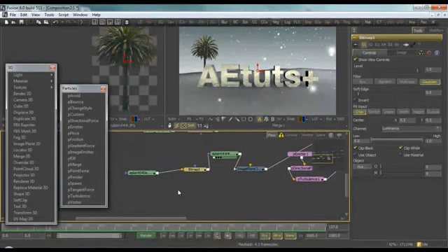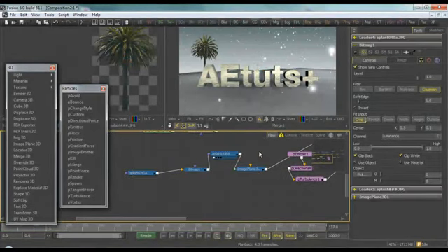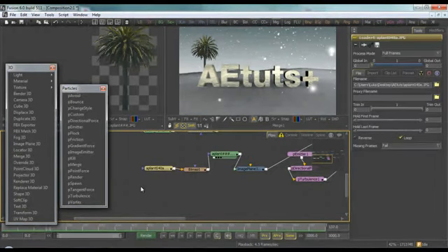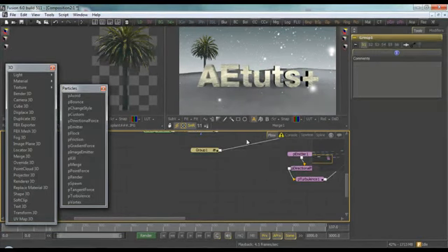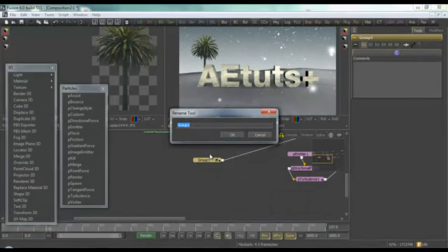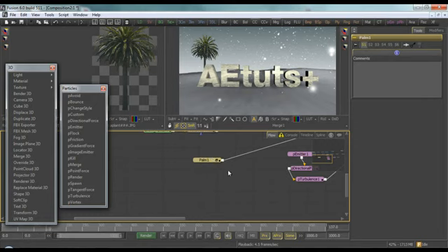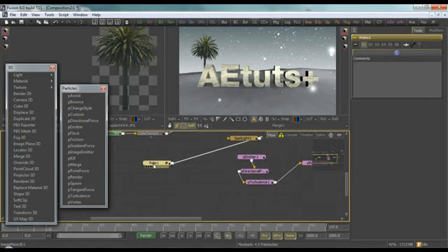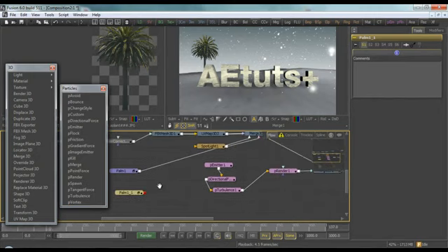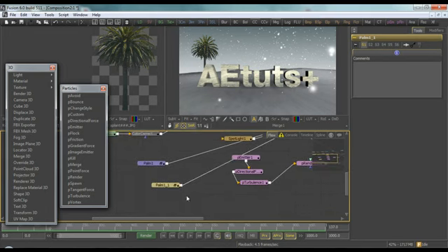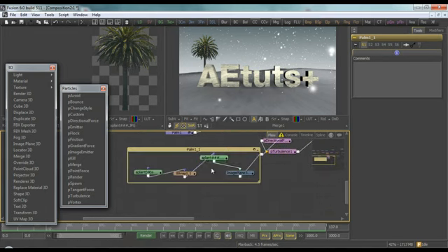and let's duplicate it, select everything. Oh, a tip: if you want to group it, just select everything, press Ctrl G, and you have a group. And if you want to rename it, just press F2 and we'll write in palm 1, and we just copy and paste it, feed it to our 3D world, and we have another palm, but we have to move it a bit.